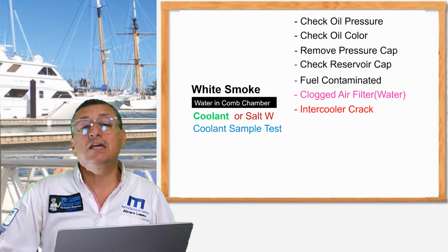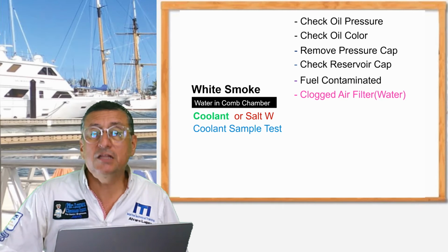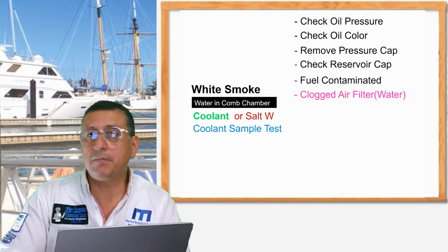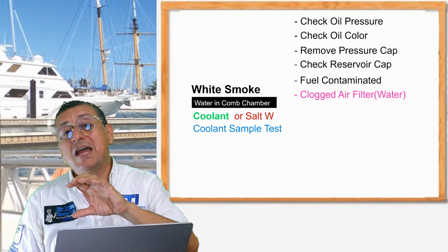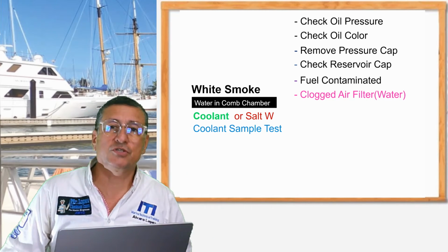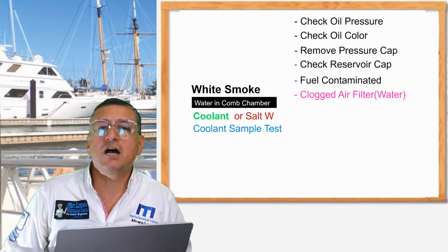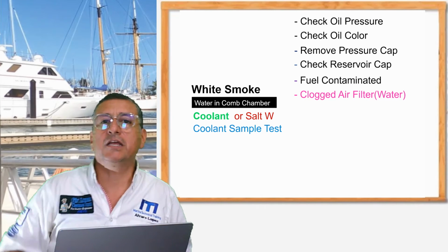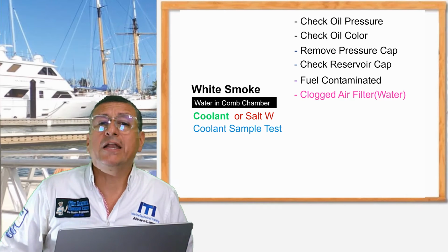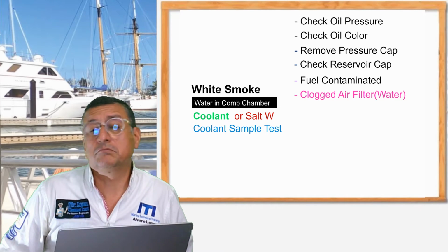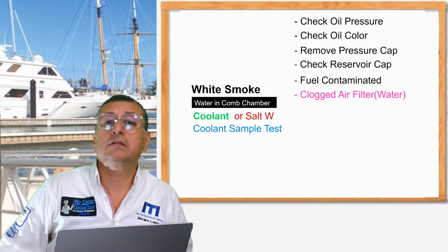Another possibility is a problem in the intercooler. Let me explain something about that situation. Remember that there is a possibility that salt water enters the combustion chamber. How many options are there for salt water entering the combustion chamber? Three options. Option number one is when you are cranking the engine.